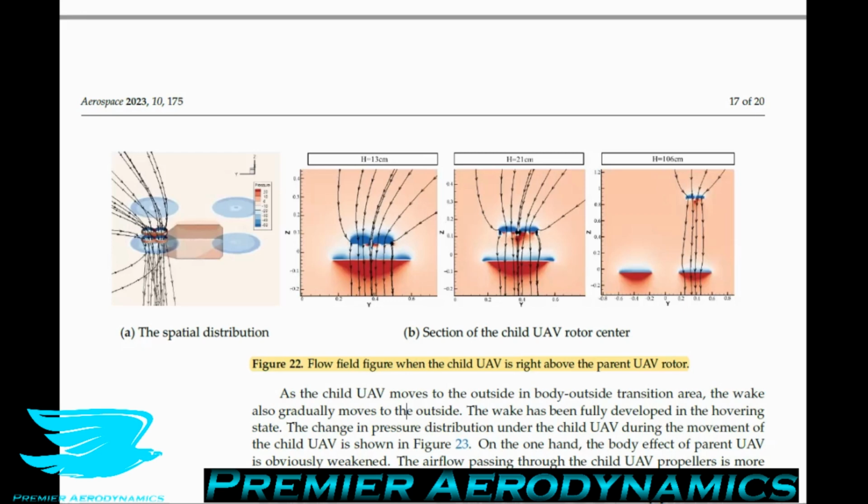The alternatives are either you reduce the lift of one of the other rotors, which means that you're not going to get as much lift, so you may not be able to hover, or you have to increase the RPM of this rotor, or if you can, change the pitching angle of the rotor that's being affected to increase the lift to stabilize this effect.